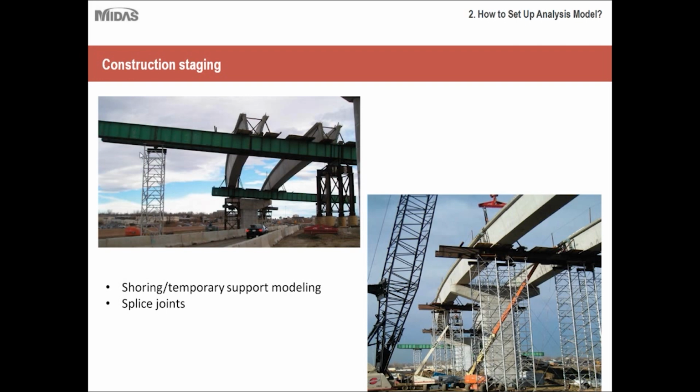So you would have to, instead of just applying a point support and getting the camber value for the superstructure, model the entire system underneath it, something like this, and then assess the forces.